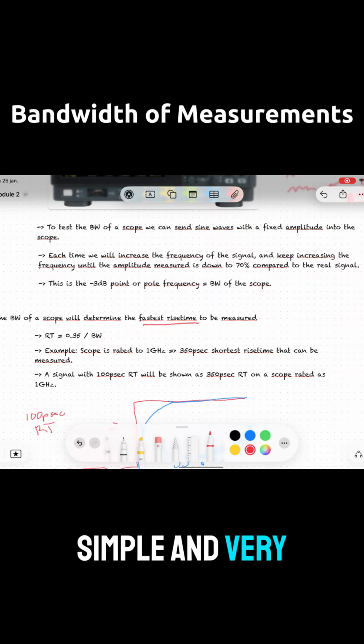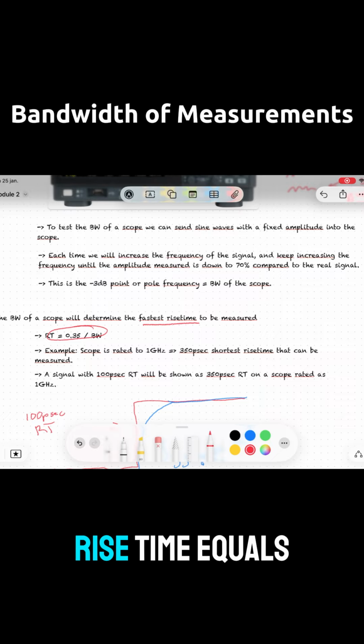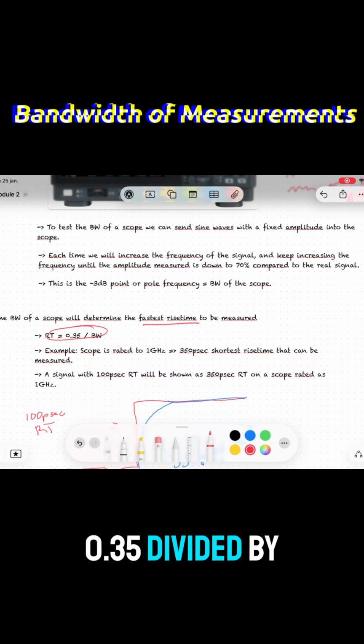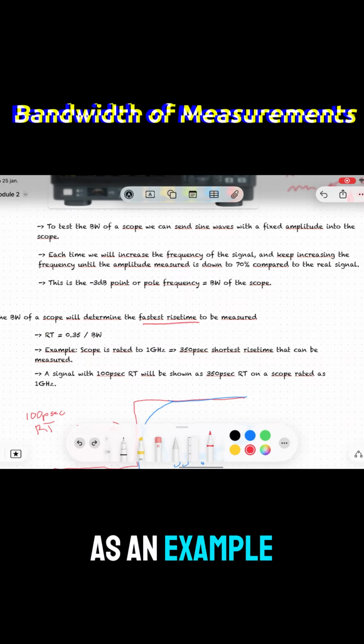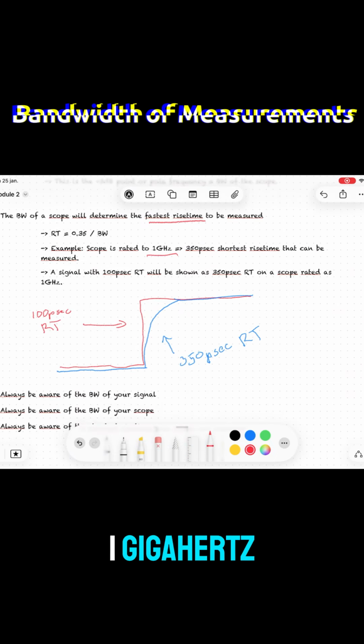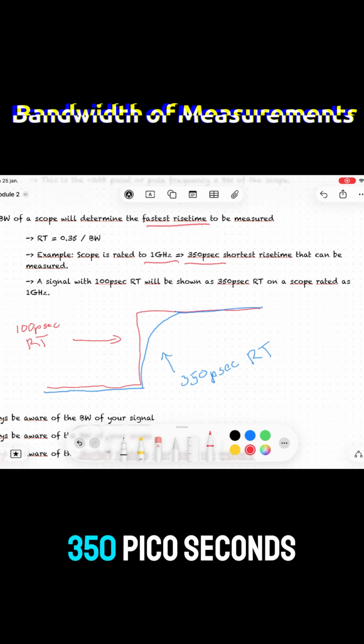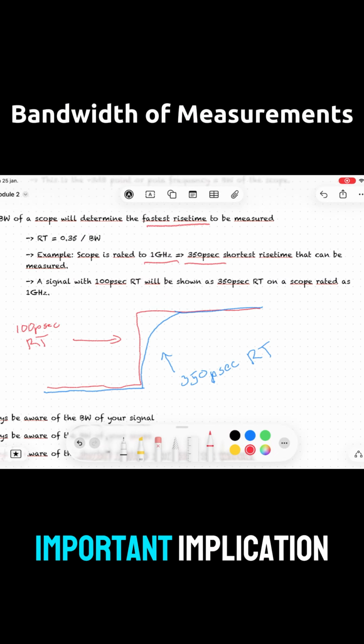There is a simple and very useful rule of thumb that connects rise time and bandwidth. Rise time equals 0.35 divided by bandwidth. As an example, if an oscilloscope is rated at 1 gigahertz, the shortest rise time it can measure is approximately 350 picoseconds. This has an important implication.